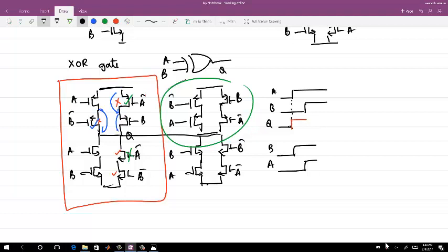But if you lay out capacitance, let me give you an example. If this is of size X and you have a certain parasitic capacitance, you break this into X by 2 and X by 2. But your parasitic capacitance at each intermediate node still remains the same, CP1. So I am distinguishing between this.